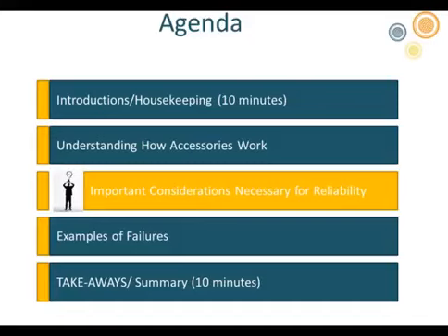Originally, 295 mils was the 100% level for 28 kV. It's now 280 mils. So if you have any 295 mil cable, it's probably relatively older cable. Typically, for 25 kV cable now, 100% is 260 mils, 28 kV is 280, and the 295 is older versions of the 28 kV cable. But now it's all either 260 or 280. So hope that clarifies that. Thanks.